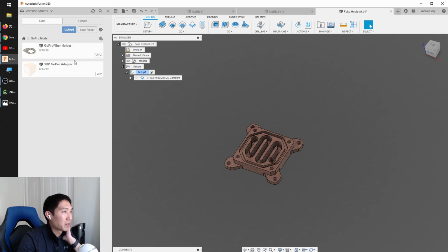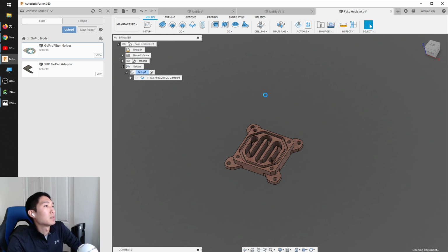So with thread milling, you have a tool that might look like a double angle cutter, but it's actually got a flat at the tip, so it follows the standard NC profile. I'll show you how I set up my thread mills in Fusion in a moment.